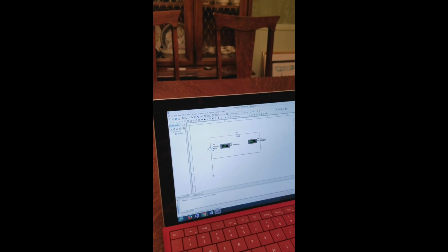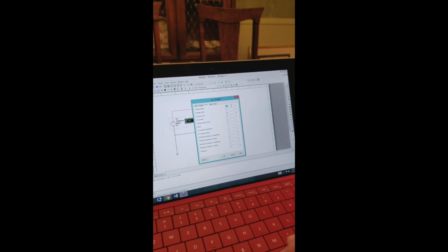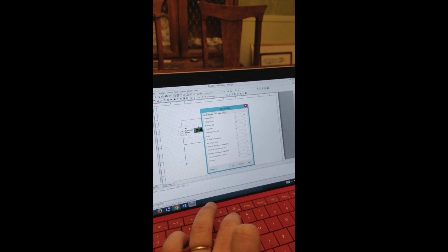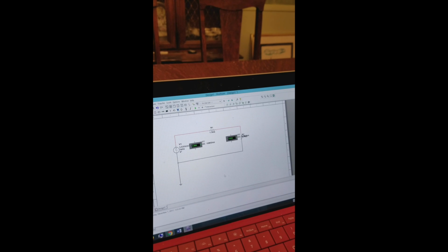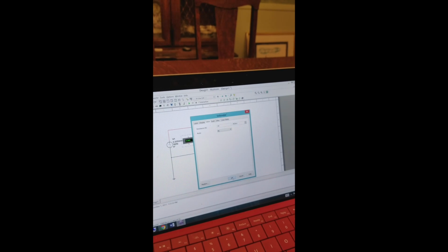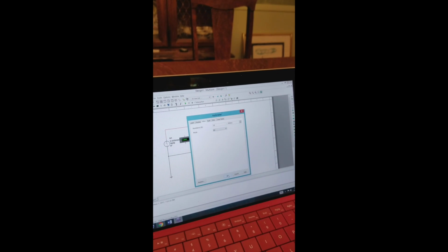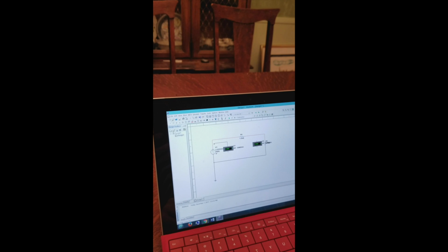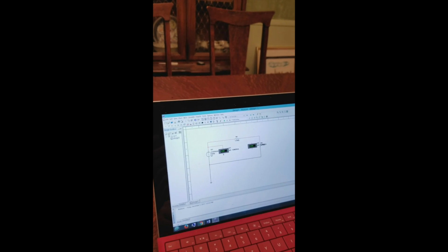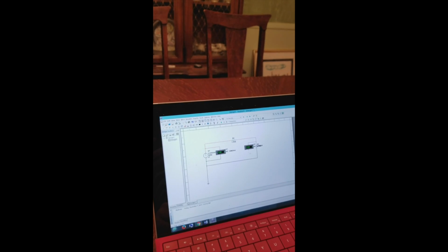We'll go ahead and I'll configure our AC source here for our RMS voltage, which is the 3.535 and our 1 kilohertz frequency. Going to make sure these guys are set for AC, and connect them in parallel to our voltage source and R2 to test them.